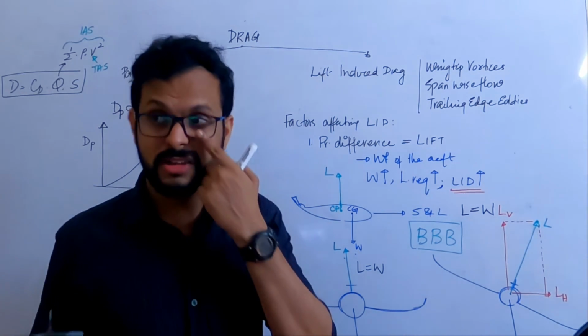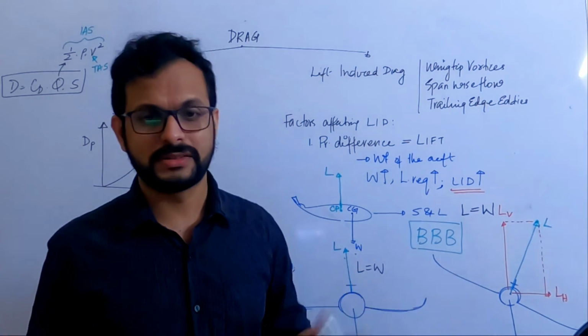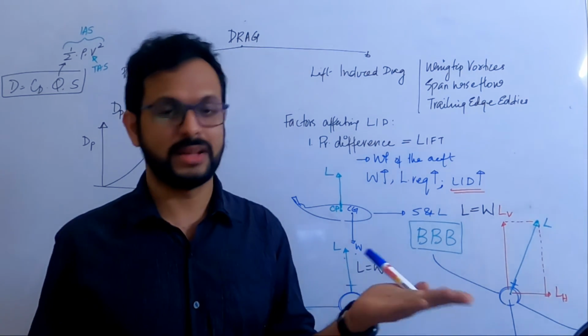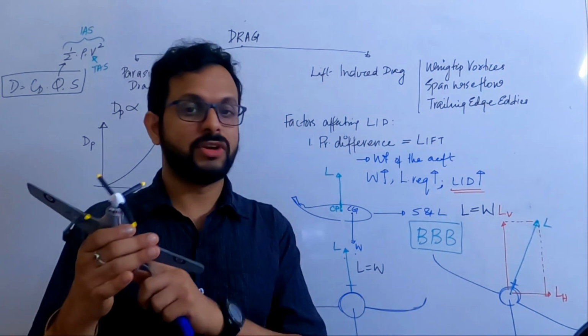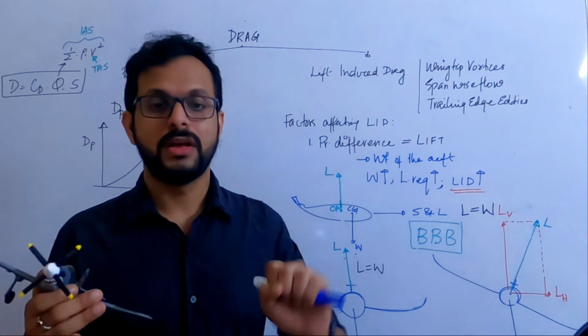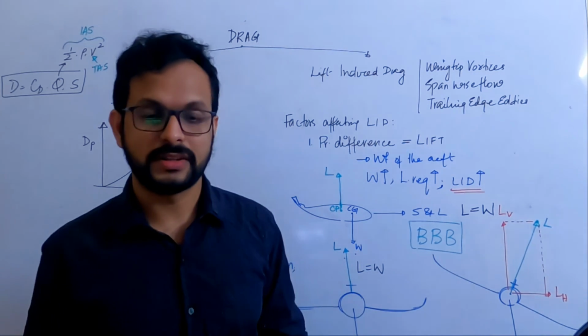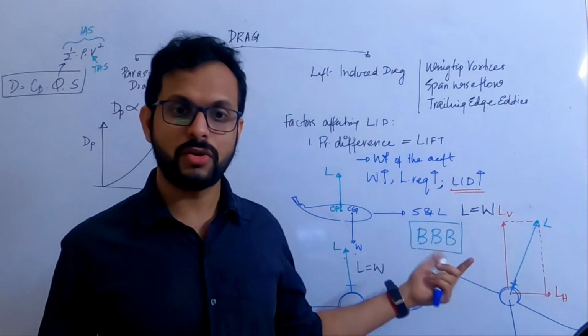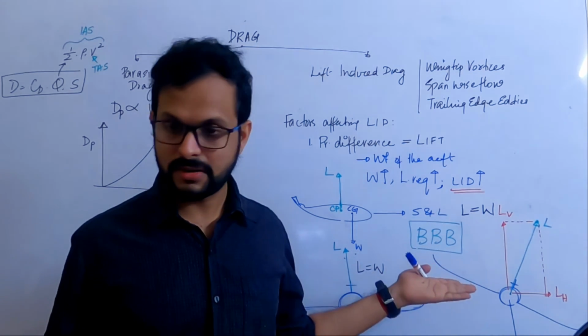You will reach a point, especially when you go to 60 degrees or more than that, where just pitching up won't work. You have to even add power if you want to stay level. Yes, Hiloni, are you able to relate to what I'm trying to say when you make a turn? Yes, yes.